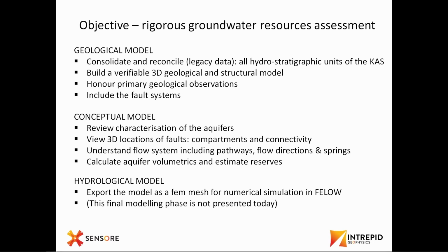The conceptual model that we created initially will provide the characterization of the aquifer. We can view the fault areas in 3D, the compartments and connectivity within the faults. We understand the flow system, including pathways, flow direction, and springs. Also, we can calculate the aquifer volumetrics and estimate the reserves of that particular volume. Then the final model we can export in different finite element meshes for our numerical simulation in FeeFlow.